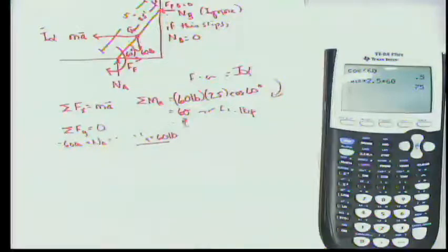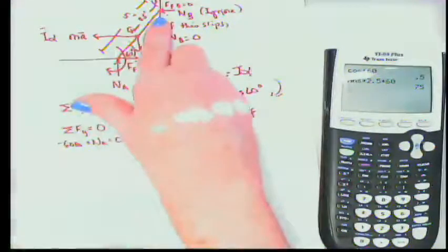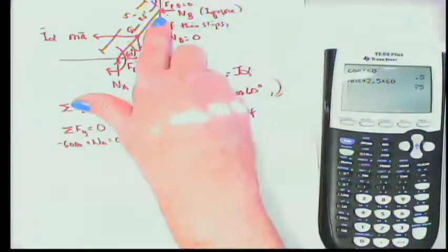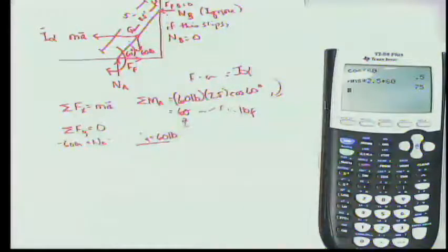So we're setting the normal force at B equal to 0 as that constraint condition for when the plate starts to move. I don't like that because it feels a little inconsistent to me, but it's the way we're going to be able to determine that. It's not mathematically inconsistent. It's just that we're talking about two things. We're saying it doesn't really slip, but right when it does slip, the normal force turns to 0. So we're just setting it as a limit. I can live with that idea.